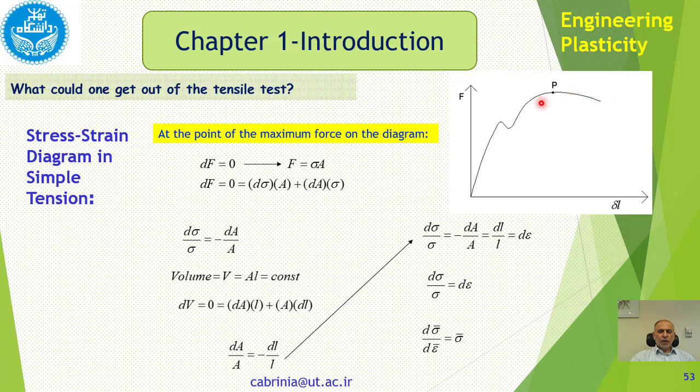Obviously, in a tensile test, we can simply say that it's the maximum point and we can find it. But in complicated cases, which is most cases in practice, in industry, you have tension or sigma applied in different directions. And therefore, you have to have a formula for finding this point in those loading conditions. And that's what we have in here.